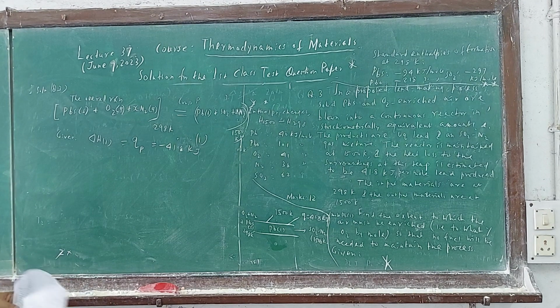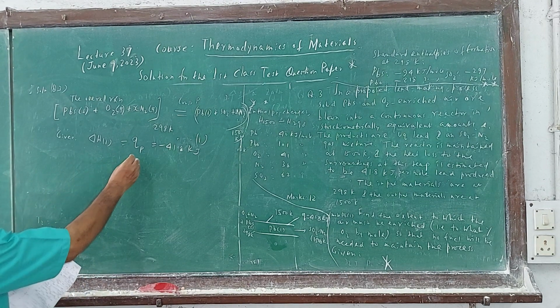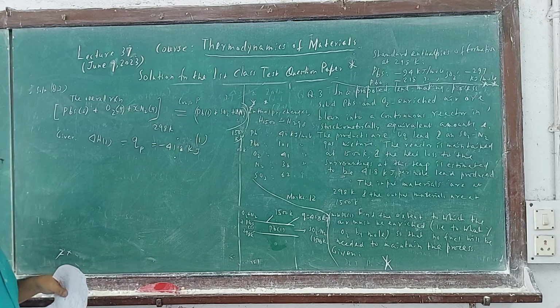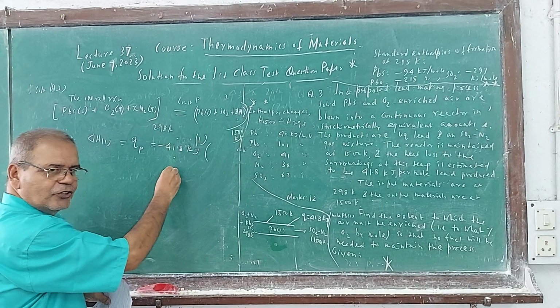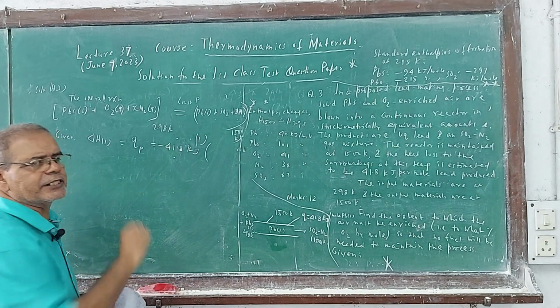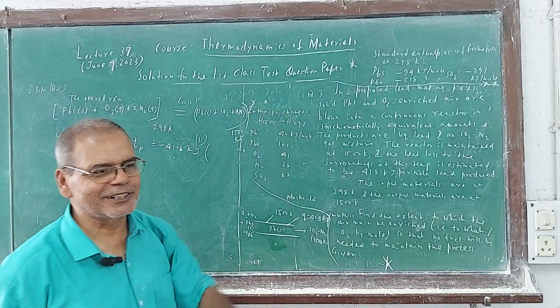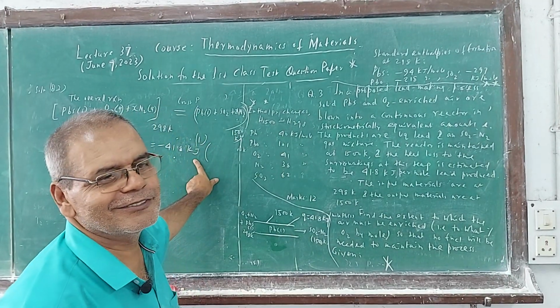Good. So delta TP. Why is this constant pressure? I've written there, constant pressure process, open to atmosphere, continuous. And how much is the heating interaction involved? Minus 14. If it is perfectly adiabatic, it will be 0. It would be 0 if no loss. If no heat is dissipated, no heat is lost to the surroundings, what is this value? 0.